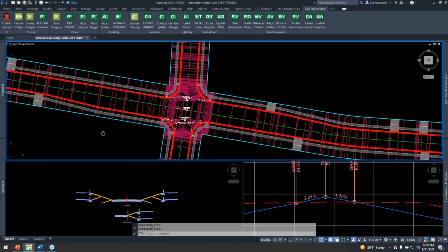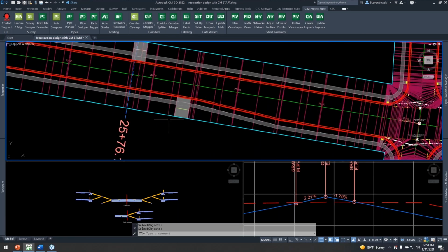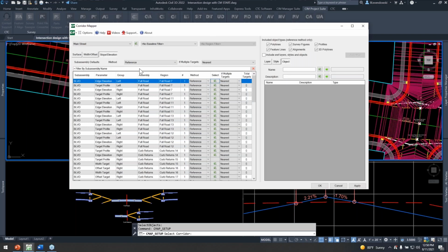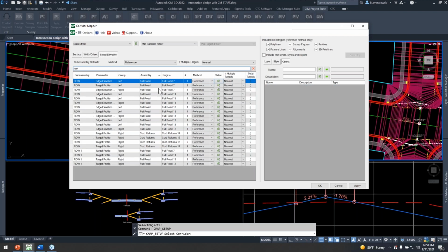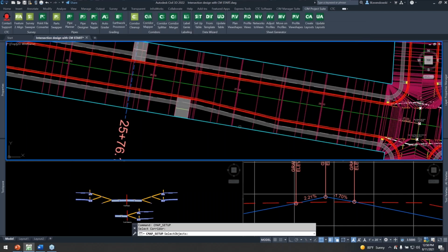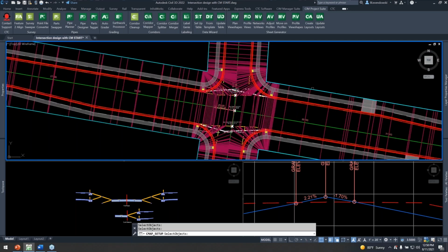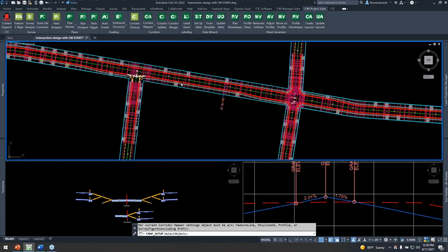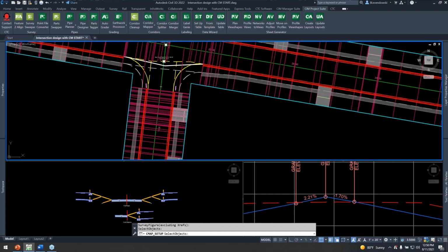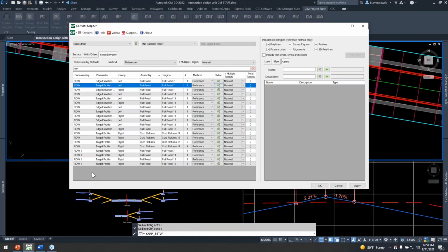Just rebuilding the corridor. Now everything's tying into the right of way. Now that controlled the slope, or excuse me, the width. So we would just do the same thing for the slope, okay? I'll do it. It's the same process here. This one here, we're going to assign those feature lines. One more over here. I'm going to set all of these to mirror.